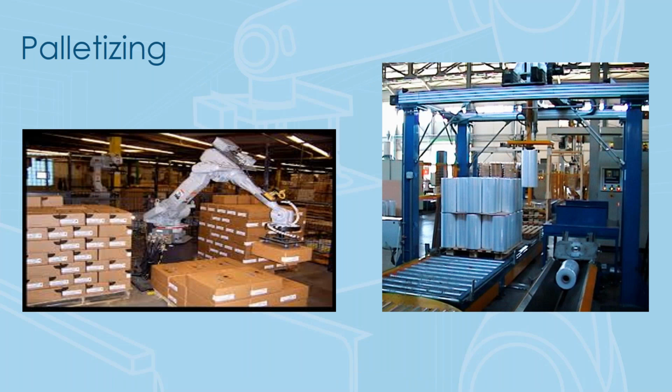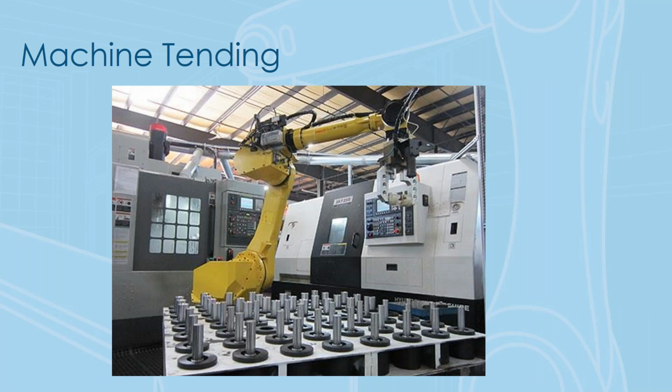One thing that, Matt, you reminded me with the fixturing, if we could just go back to that last image, in this case, you have an 8x8 array of parts. And the nice thing about this fixture, if it's well designed, you don't need any additional sensing for the robot. As you mentioned, you don't need a vision system to locate those parts. You can just load up the magazine, and you're going to assume all 64 parts are there, and have the robot run through that cycle of picking up each part, placing it in the CNC machine, and then putting the finished part in an output tray.